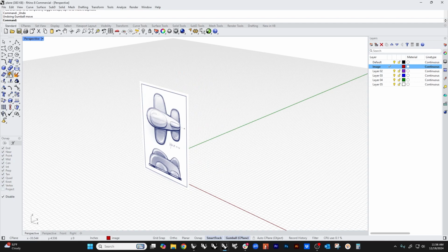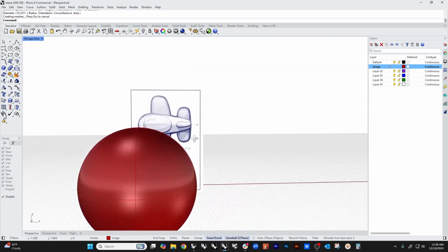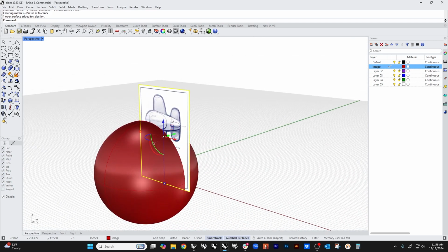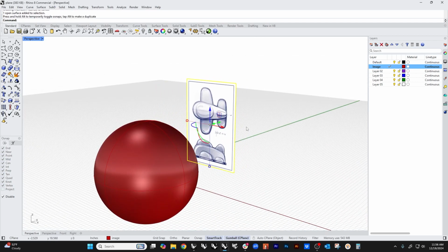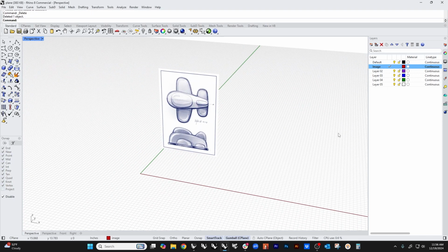If you've seen any of my other videos, I do this all the time. The reason I do that is that, especially in shaded mode, you can't see what's going on. If you slide it back, you can still see what's going on even though the model's here in the front. That's why I do that. The other reason I like to assign this to a layer is that now we can lock it, and we can hide it or show it when we want to.